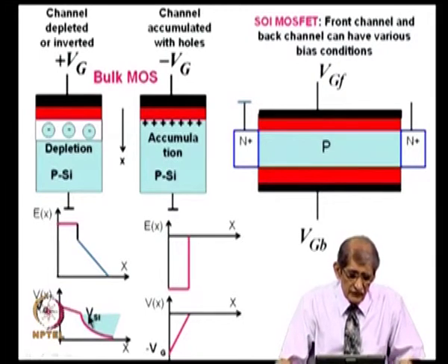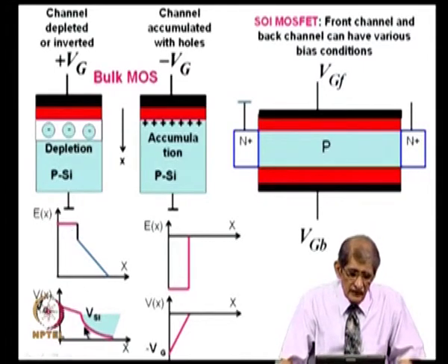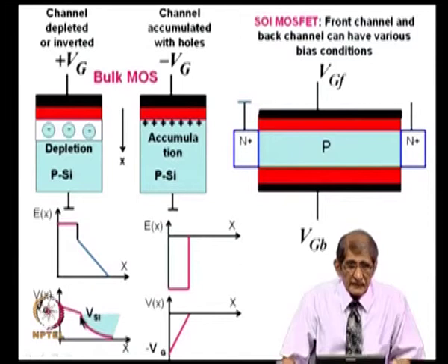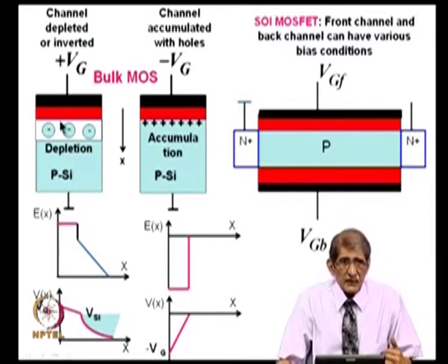So, you have got the voltage drop. The field actually is V g minus V silicon divided by T oxide, that is the field there. So, V silicon is like this. Now, it will be inverted when V silicon becomes twice phi f. So, that is depletion or inversion. Usually, you operate in this region.